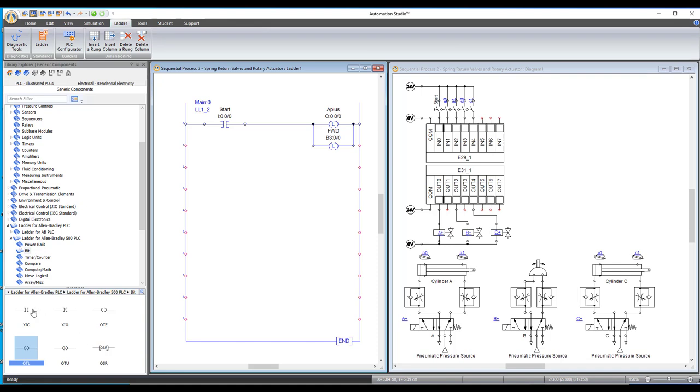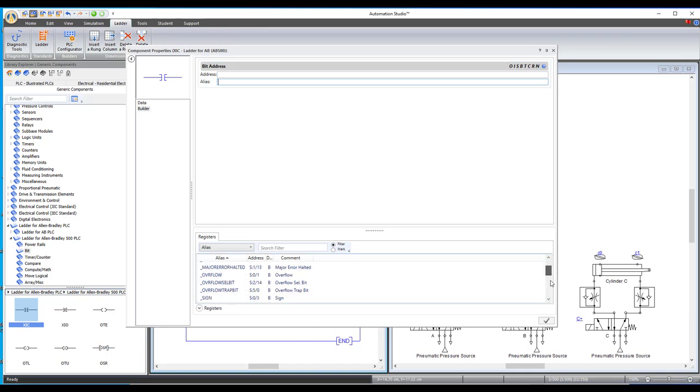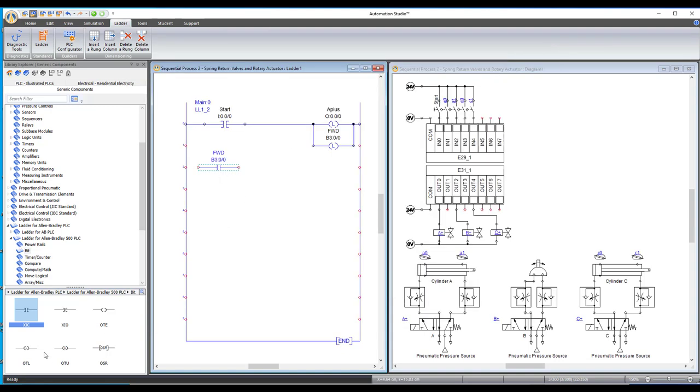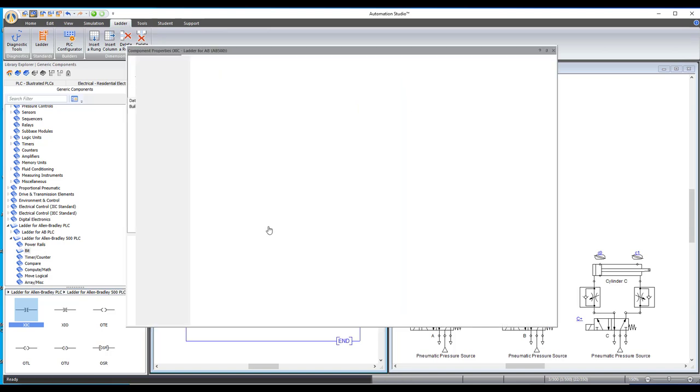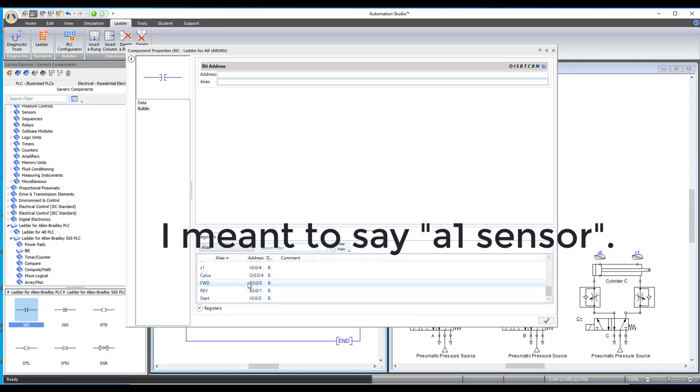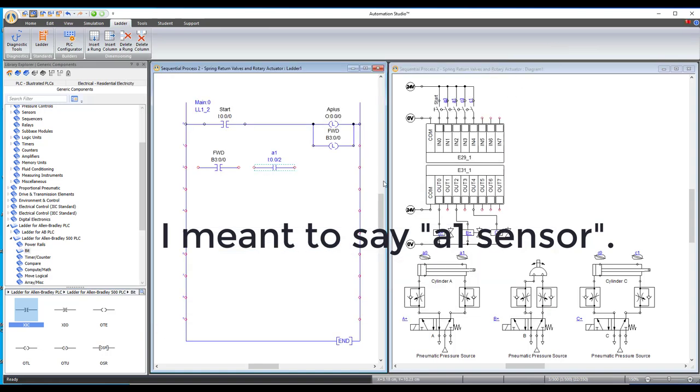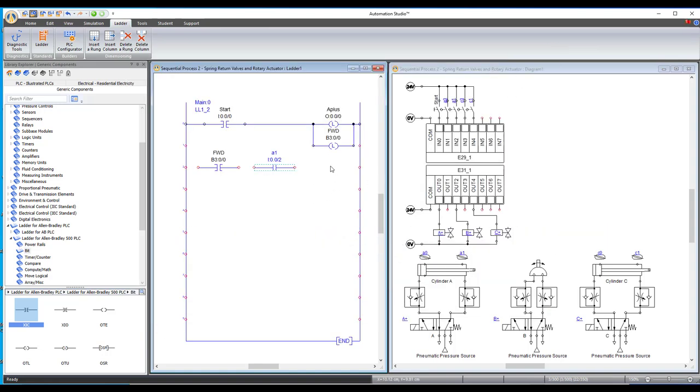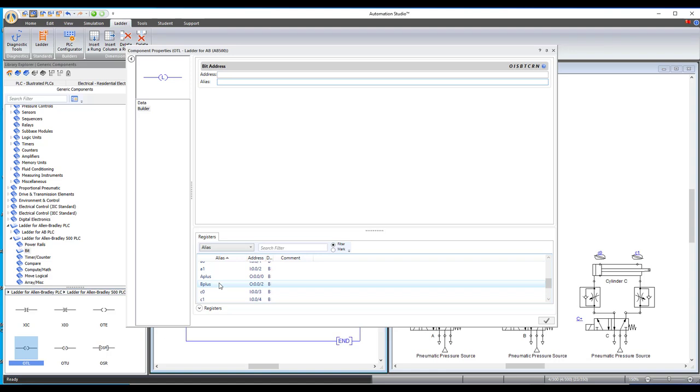We're going to have if forward is true. So I'm just going to grab forward from here. And the A1 actuator is true. Oops, I went past it right here. Then we're going to latch on the B actuator. So we've got another latch output. That's B plus.